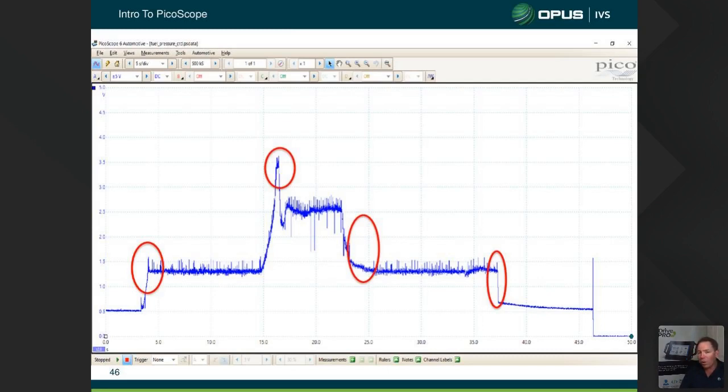Again, I let the car idle for another 10-15 seconds. Then at this point, I switch the engine off. And I should see the fuel pressure drop instantly, because the minute that pump stops turning, that pressure should come straight back down to this point here. Now, you'll actually see that this point here is still a little bit higher than what we were on this side. And that's because there's still some residual pressure in that rail.